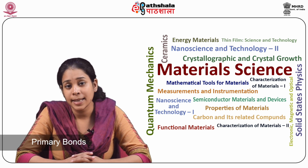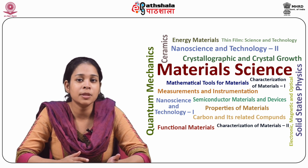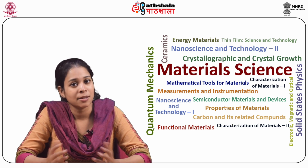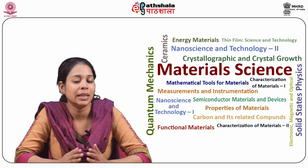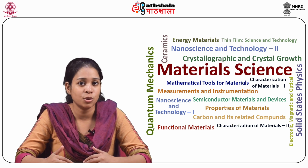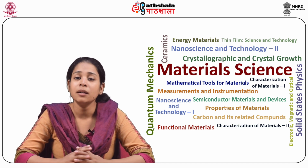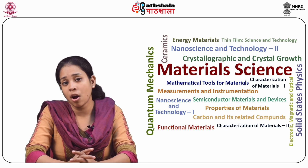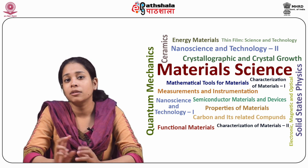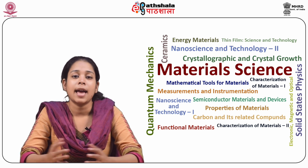The primary bonds exhibit bond energies in the range of 50 to 1000 kilojoules per mole. Primary bonds are metallic, covalent and ionic bonds, with metallic bonds typically being the weakest. On the other hand, the bonds with energies lower than 50 kilojoules per mole are called secondary bonds, and the examples of secondary bonds are van der Waals bond and the hydrogen bond. So, let's discuss the primary bonding first. There are three types of primary bonding mechanism: metallic, covalent and ionic.